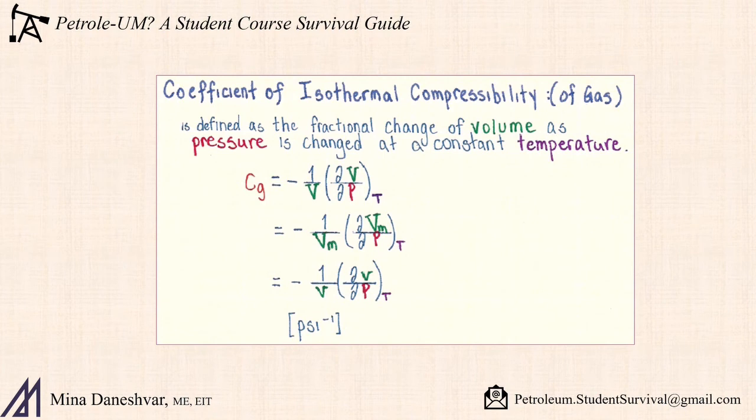Next, we'll introduce the compressibility term you're most likely to encounter and work with, coefficient of isothermal compressibility. It can be derived and denotes the change in volume per unit volume per pressure change at a constant temperature. If you're familiar with other applications, this might look like the specific heat value. While understanding enthalpy is important to success in engineering, it's not important in this particular application, but it is assumed that this process is isentropic and isenthalpic, meaning that enthalpy and entropy are constant.